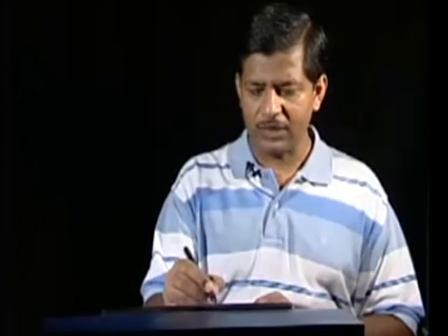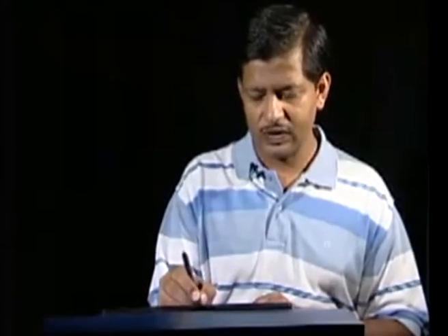for p equal to 2, how are we going to define this shape function? Now I am not going to do it in the physical element, I will do it in the master element. So here is my psi 1 which is equal to minus 1, here is my psi 2 which is equal to 0, and here is my psi 3 which is equal to 1.